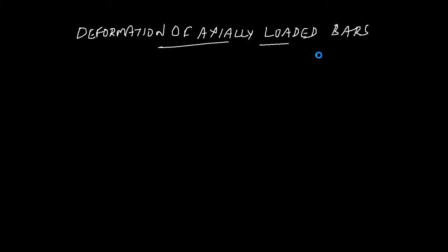When the deflection of an axially loaded member is a design parameter, when you design something and one of the design parameters is the deflection of an axially loaded member, then it is necessary to determine the deformations. Axial deformations are also required in the analysis of statically indeterminate bars. It is also to be noted that the deflection characteristics of bars provide necessary information for determining the stiffness of systems in the analysis of mechanical vibrations as well.